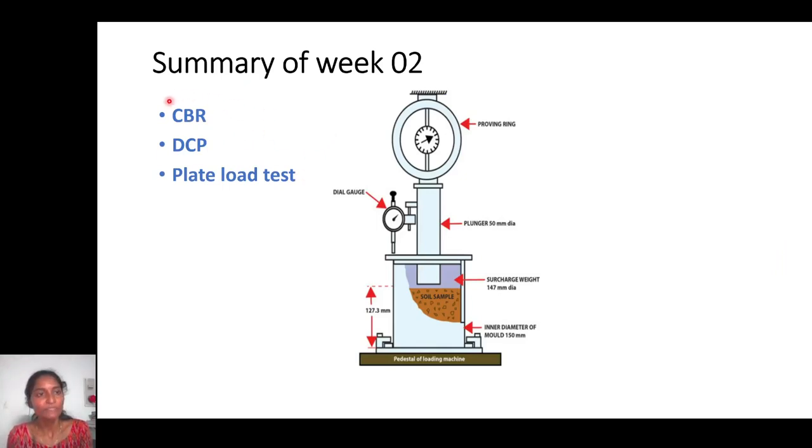In addition to that, as we have already summarized, CBR, dynamic cone penetration test and plate load test. This CBR is for laboratory strength determination of soils, whereas dynamic cone penetration test and plate load test, these two are for field determination.